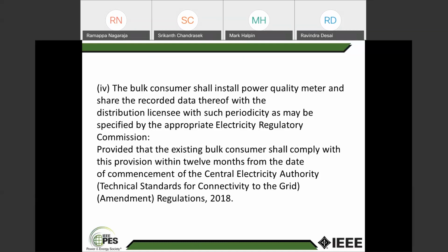If compliance with a contract becomes a concern, the utility wants to make sure that any recorded data is in compliance with the applicable standards. In this case, the power quality monitor would need to be compliant with IEC 61000-4-30, and the utility wants to ensure that's true.